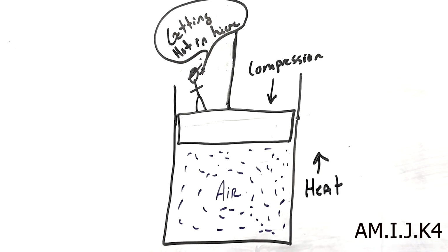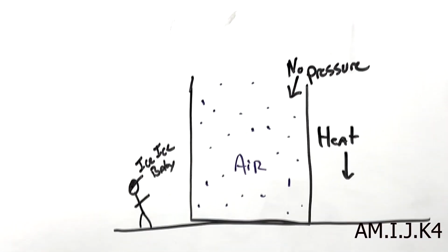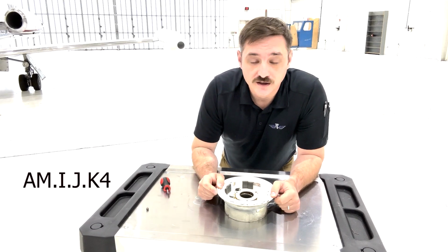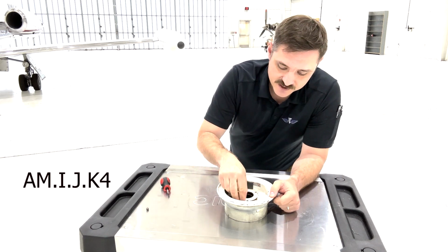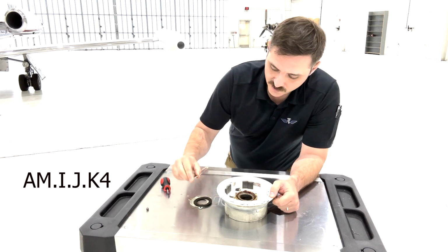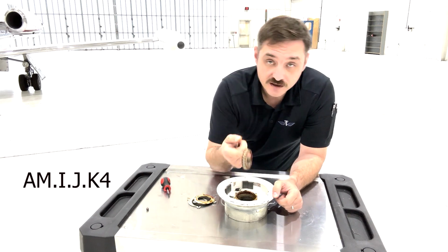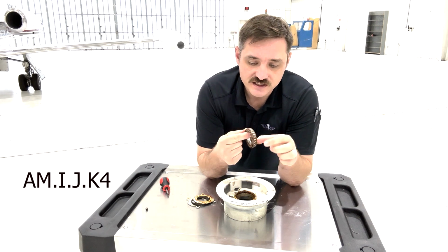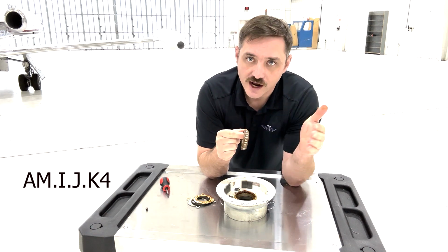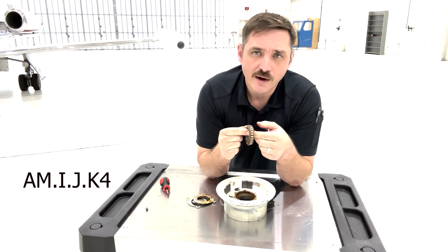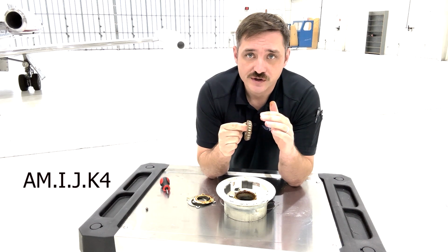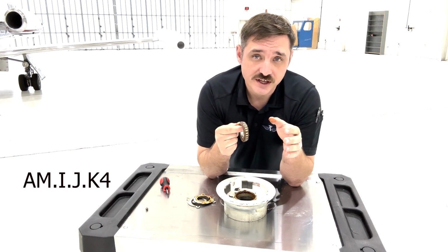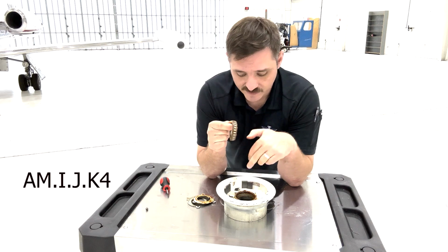When gas is compressed, it becomes warm, while expanding gas cools. This relationship between heat and work is reciprocal. Friction is a regular occurring generator of heat. Inside this hub, you'll find a bearing. This bearing is packed with grease. Now, the bearing is there to create a nice smooth operation as the aircraft goes across the ground. However, the grease is there to make sure that the heat doesn't get too hot and then it dissipates it as the bearing operates. And this is all generated from the friction between the rollers and the outside of the